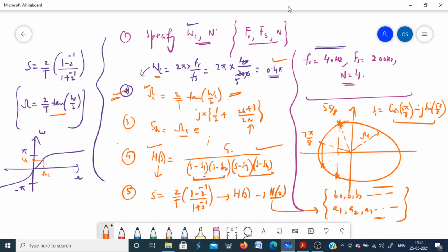Similarly, you can use it for the high pass filter. Then there are more filters like the Chebyshev filter and elliptical filters. They are very similar to this Butterworth filter. You design a filter in the analog domain, and then using the bilinear transformation, you convert this filter into a digital filter. Normally, for these biomedical signals, like for baseline wander, we have used a filter in the last lecture.